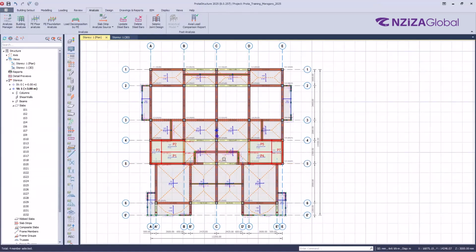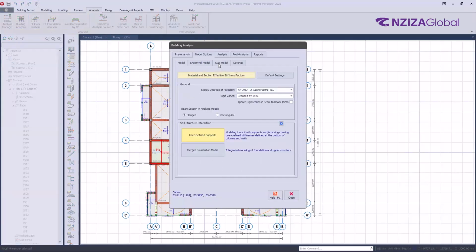So this will be one diaphragm, because the slabs are connected together, they are forming one diaphragm. We have a gap here, but the remaining slabs at the top are forming another diaphragm, another plane, if I can say. Okay, so I will do Ctrl-Z to bring back my slab. Because we don't have gaps between slabs, we will have one diaphragm. So that was for the first option here.